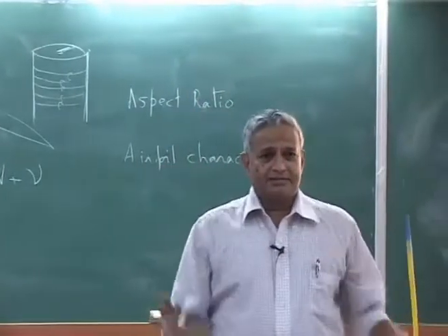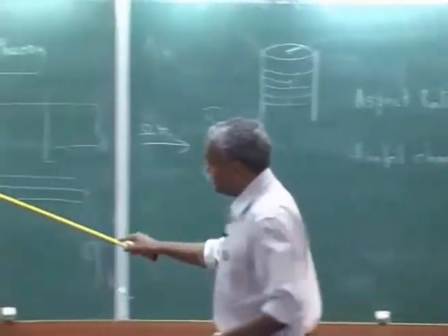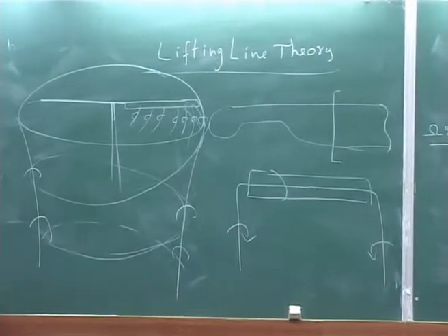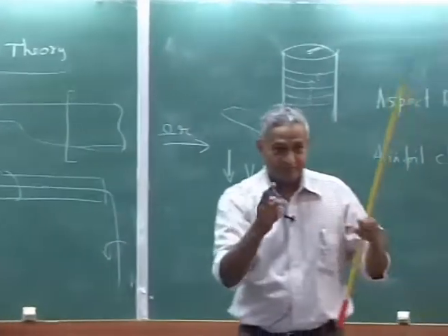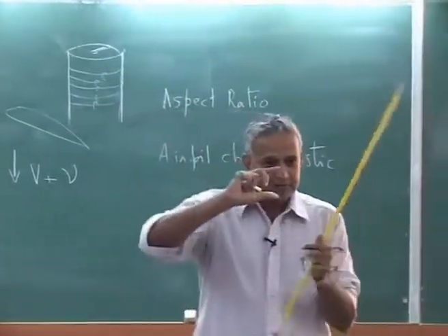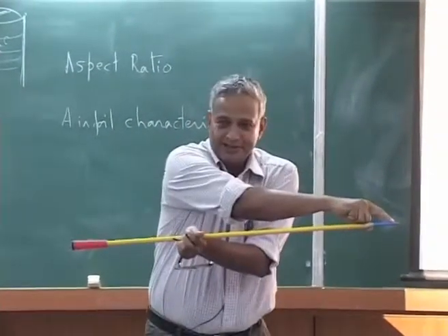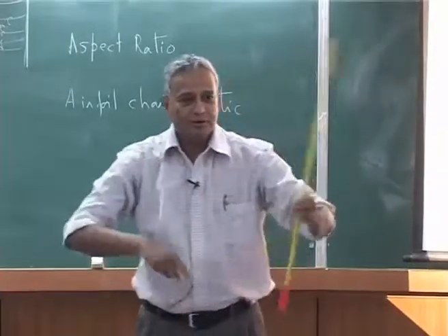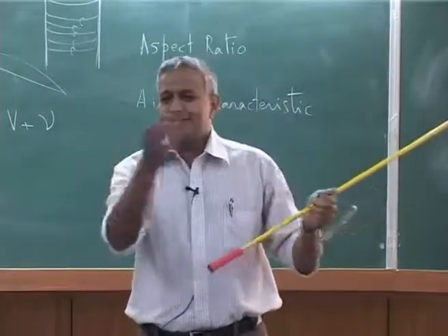Cylindrical wake structure and infinite number of blades means there is no gap between one and the other. Please understand, one blade gives a wake, it will come down, then there is another blade that will also give, that means there will be several helical wakes and there will be gaps between those wakes, because you get one coming down, then if you say another blade, that will come and they will go intertwined. But if you have an infinite number, it is almost like a continuous cylinder.